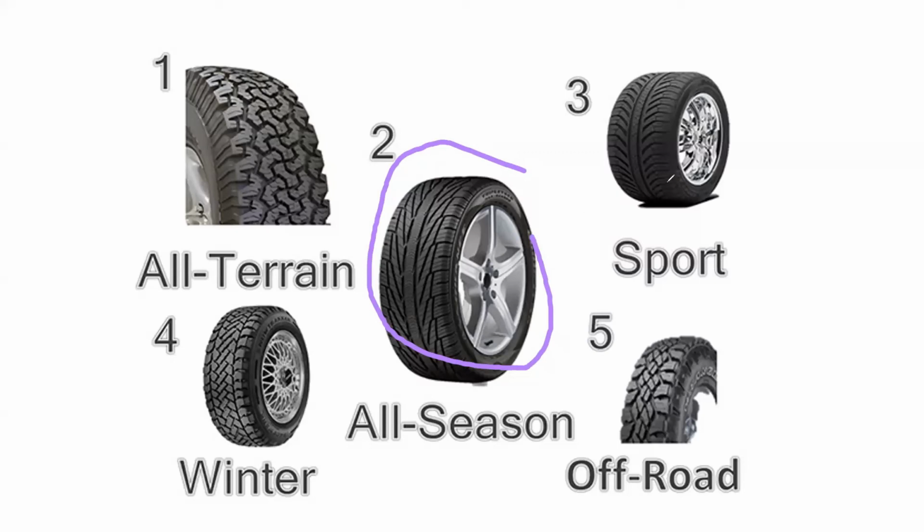Okay, now if we look at number one, these all-terrain tires have these grooves because they are designed to go off-road. In such a case the ground is probably soft, so you need to have more contact area. These grooves also allow more material to come inside. The ground material can come inside and increase the contact. So that's important. The same thing happens with the all season tire if you put it into the mud, or any of these tires.